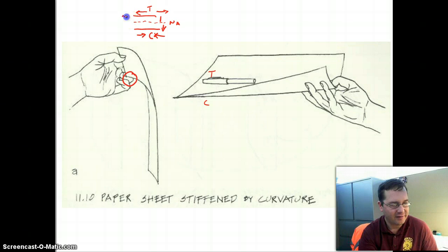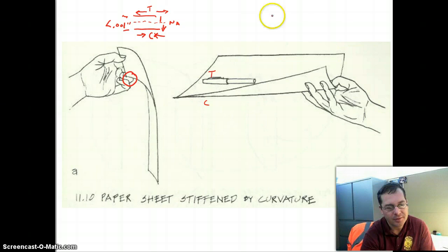But this entire distance for this piece of paper is less than 1/1000th of an inch, which means that the side of the paper that's getting stretched and the side of the paper that's getting compressed, the strain is so small that the paper's really not able to develop any resistance to that. Comparing that to this complex curve, look at how far apart now our extreme fibers are.